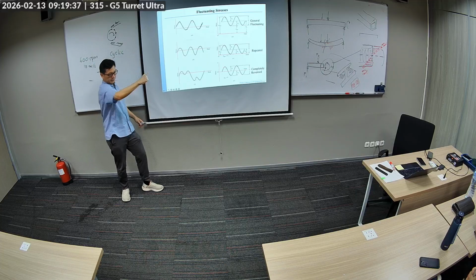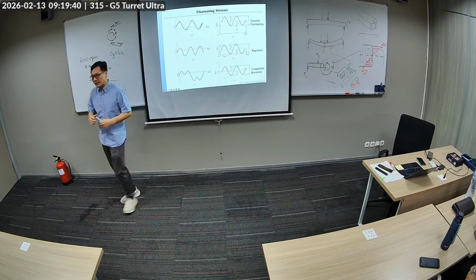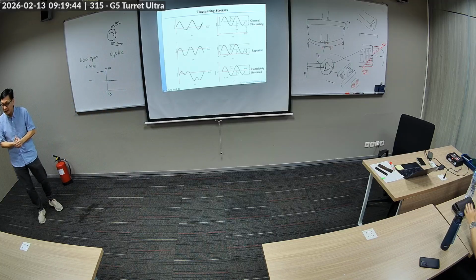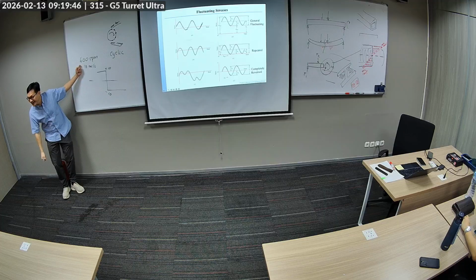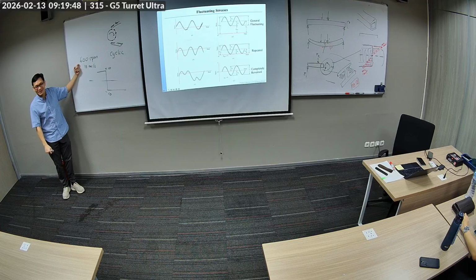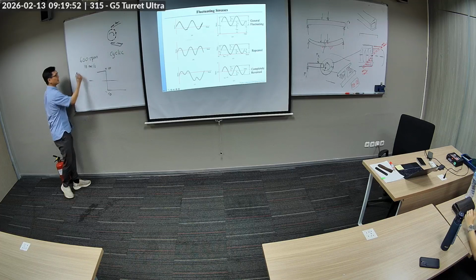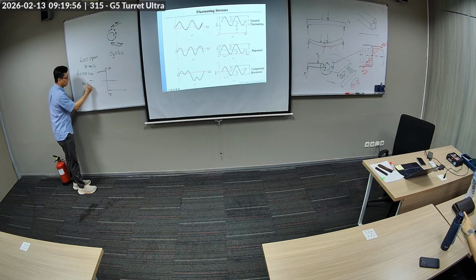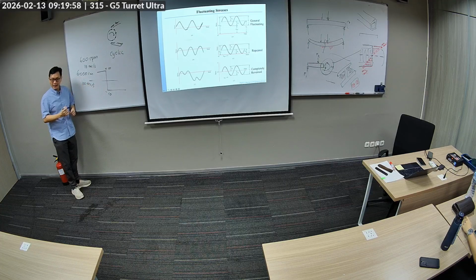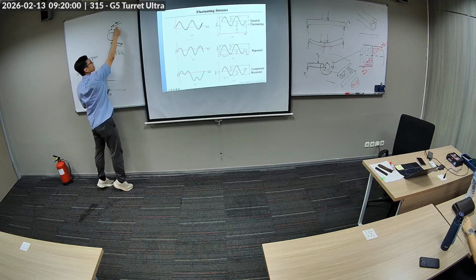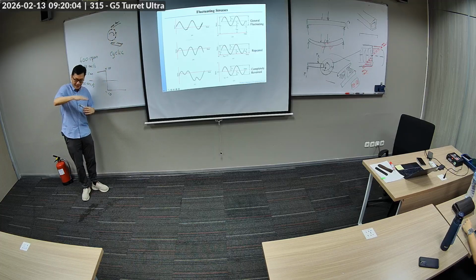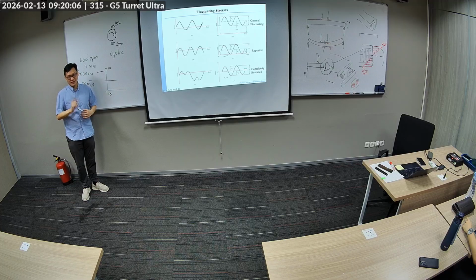It's pretty cyclic, very much fluctuating. And this is at idle, by the way. 600 RPM is close to your idle speed. And imagine what happens with 6,000 RPM. So it's 100 revolutions per second. And so you are experiencing maximum tension to maximum compression 100 times per second.